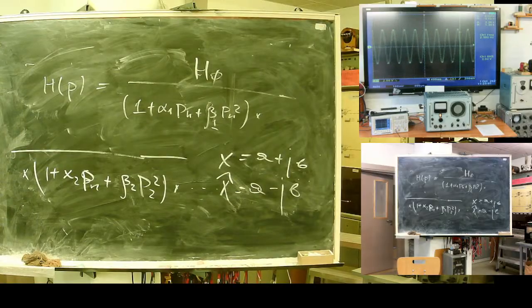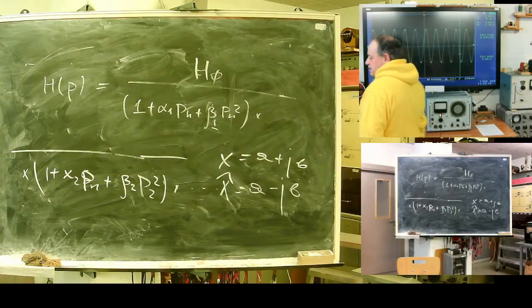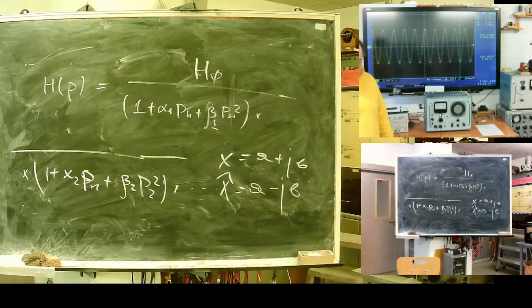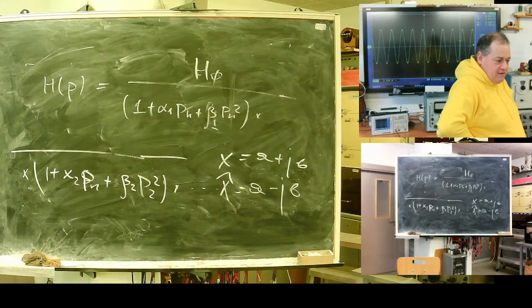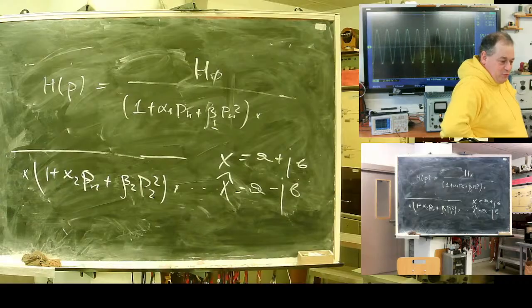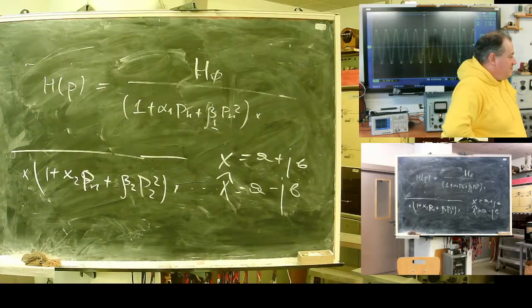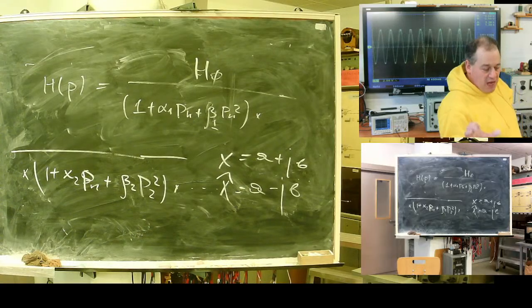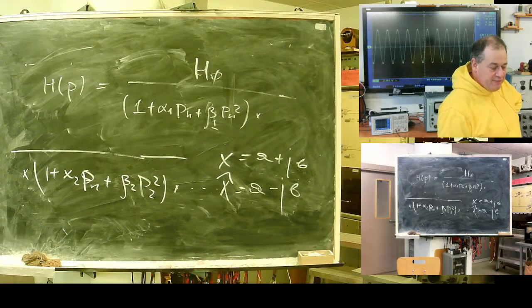What I will tell you is that you need to compensate energy loss. It means that your filter should contain an amplifier. It should be active, with operational amplifiers. You will have electronics in your curriculum. You don't know what an operational amplifier is? Op-amp, yeah? So your input part, which will perform analog preprocessing, should be active. You should think of a pair of op-amps, and maybe not a pair.